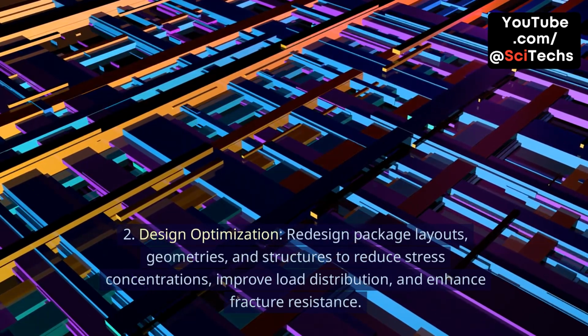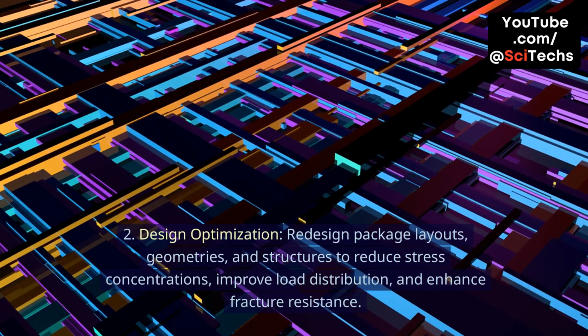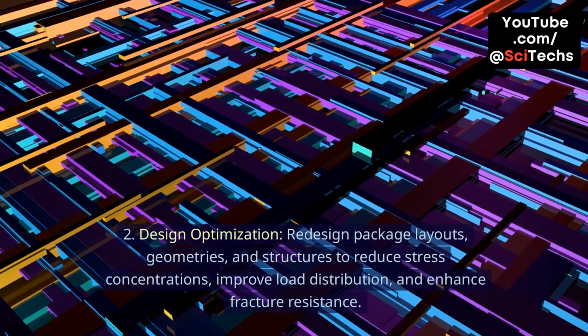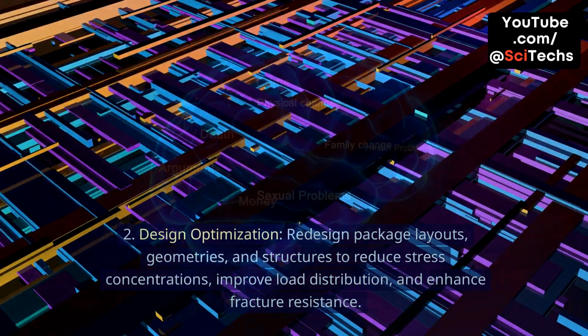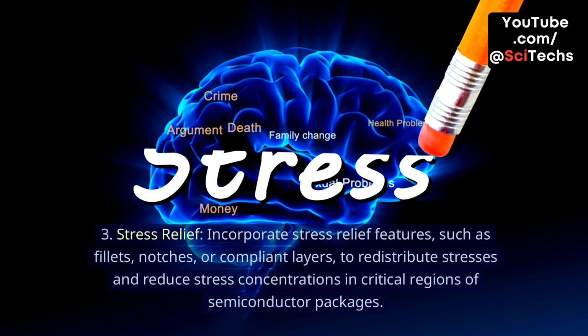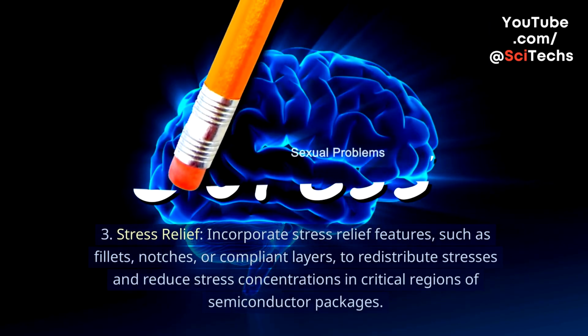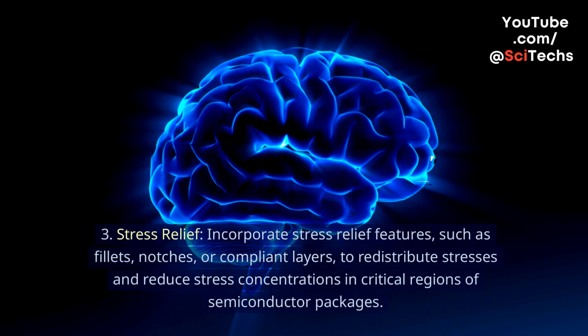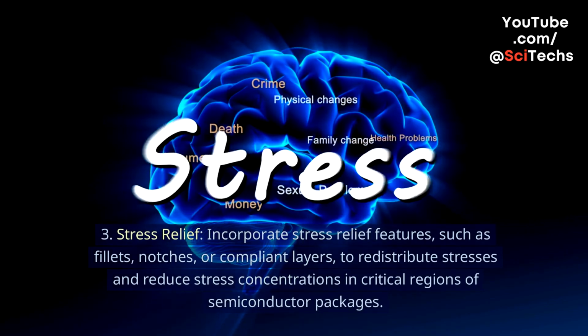Redesign package layouts, geometries, and structures to reduce stress concentrations, improve load distribution, and enhance fracture resistance. Stress relief. Incorporate stress relief features, such as fillets, notches, or compliant layers, to redistribute stresses and reduce stress concentrations in critical regions of semiconductor packages.